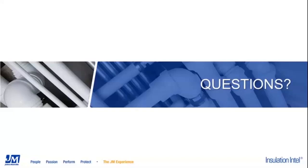So I had mentioned in the R12 section that the 2015 version of the IECC required R12 for specific applications in climate zones 5 through 8, and then it's up to states to be adopting that. So it kind of depends on how soon everybody gets on board with that, and if there's more push to increase the requirements and that type of thing.